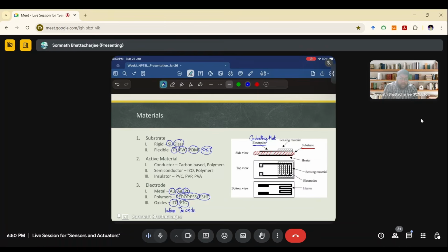But if we are intended for a specific use case, let's say we have an optical sensor. Let's say we only need the sensing material here. The sensing material doesn't need to be transparent, but the conducting electrode needs to be transparent, and also the substrate needs to be transparent. So what will you choose in that case? Out of these substrates and electrodes, can anyone answer this question?